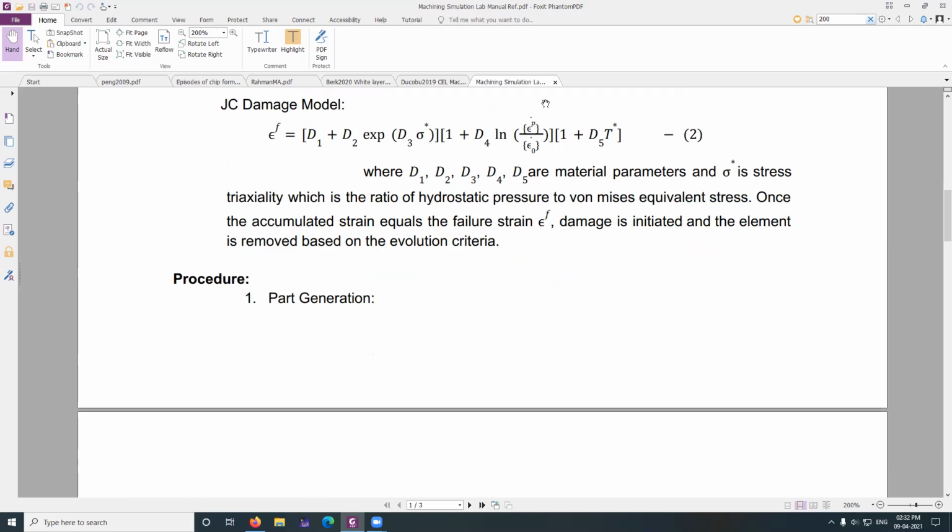A very important thing I want to highlight here is that we have to mention the evaluation criteria. For example, once we reach the ultimate tensile point in your 1D case, the load carrying capacity goes down. The curve is at the top and it will go down up to fracture. So how is it going down? Why is it going down? It is because it is a ductile material.